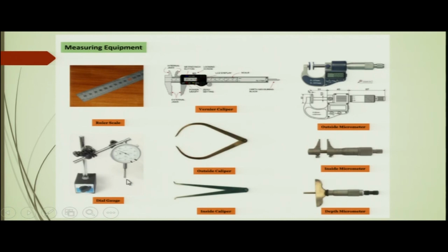So, this movement of the stylus is not much, because the entire thing may be a few millimeters only, and this movement is highly amplified for the rotation of the needle. Okay. So, that a little movement of the stylus can be felt by the needle, and the needle will show exactly the measurement.